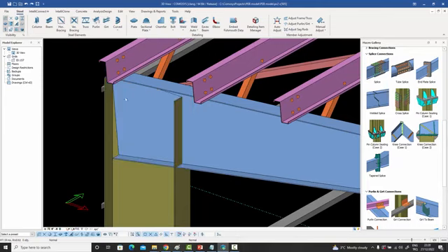Now, another way of doing this connection is, instead of cutting the web out and replacing it with a plate, you can also have doubler plates. So you can let the beam run through, and you can have two plates on the back and front side, and that's the doubler plate option, because basically, like I said, you have these high shear stresses in this area.